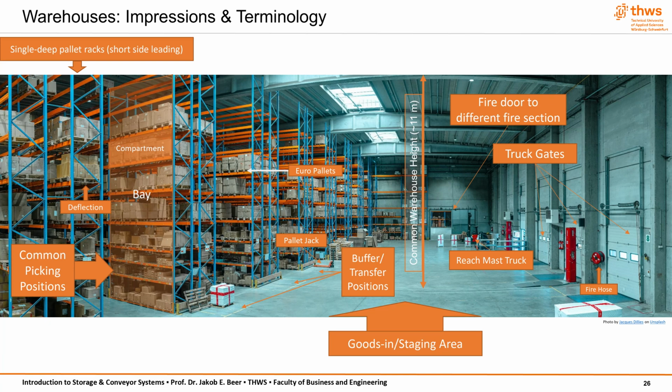That said, it is important to match building height not only to the equipment, but also to the operation profile of the warehouse. A fast-moving e-commerce facility may prioritize throughput and access over pure storage density, in which case ultra-high racking may actually slow down order picking. Conversely, a bulk storage operation with infrequent access to stored items may benefit greatly from high bay configurations.